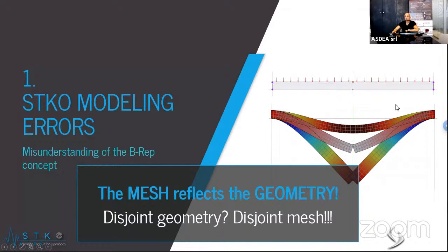Now I'm going to show you an example where I want to model a beam, actually using surface elements, because it's easier to explain what I want to explain. And I will show you that basically the same CAD model, depending on if you draw them attached or detached, will be translated into a continuous beam, a completely detached beam, or a partially constrained beam, okay?